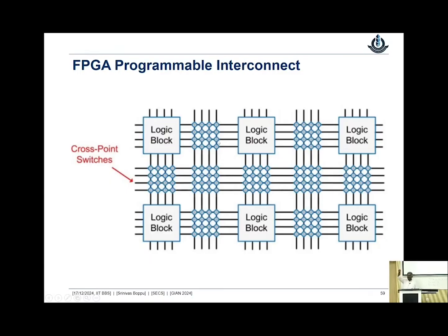So now wherever the lines are, we can think there is this 6 point switch. And for the 6 point switch, however many switches we have, that many transistors we have, and that many SRAM cells we have which will get programmed. Now, as I said, when we are mapping the logic to the FPGA, we have to generate the content for the LUTs. The LUT content is nothing but the function truth table values that we have to program, and similarly the bit file also consists of the configuration for these connections, in a simple way.